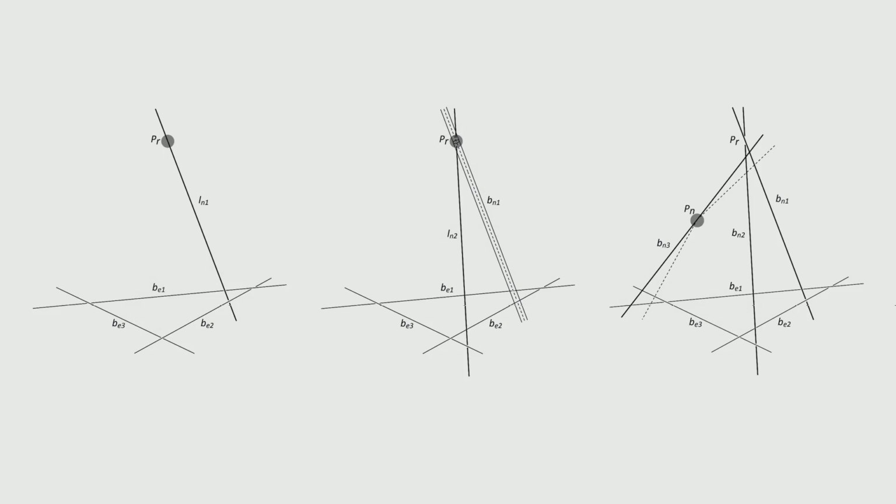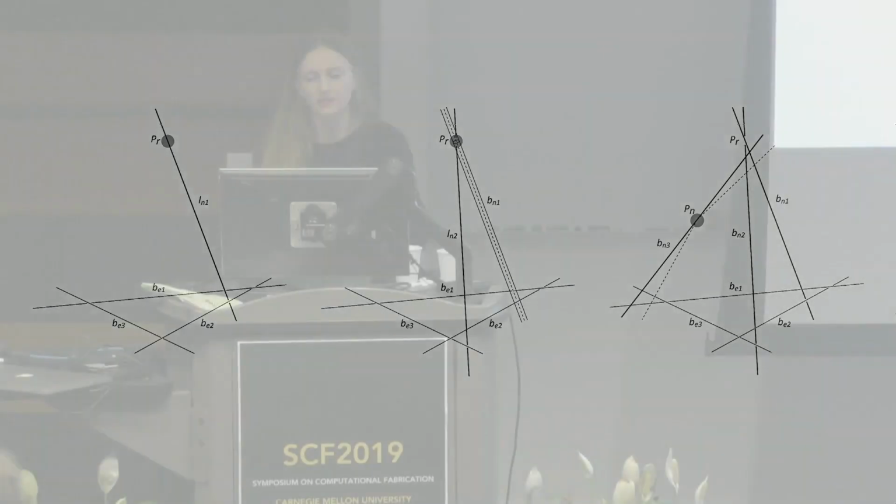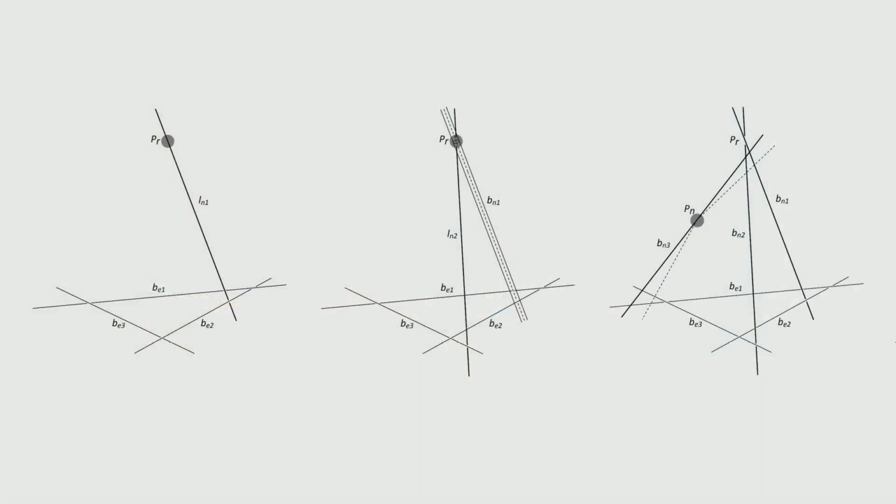So if we look at the bars as they are generated one by one, the first one can be calculated quite directly because you have a point and 2 bars that the resulting bar should be tangent to, and this is a deterministic problem, can be directly calculated. However, the second and the third bars in a 3-bar group, they have more unknowns, as you don't have the point anymore known at the top of it, so you need to figure out where is it touching the first bar as well. So this required an iterative process to calculate each of these bars' positions.